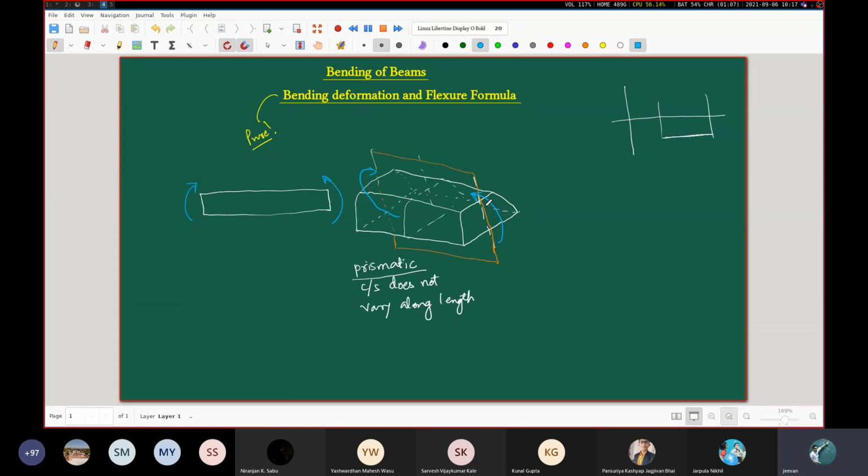For example, it can very much happen that you have not only this kind of bending moment, but also a bending moment like this in the horizontal plane. So the effective bending moment will be something along this direction. In that case, we say that even though the cross section is symmetric, the bending that is going to take place is going to be unsymmetrical bending. Again, I'm repeating that we are not concerned with those kinds of advanced topics right now. First, we need to understand the very simplest of cases. Only then will we be mentally prepared to tackle the harder cases.